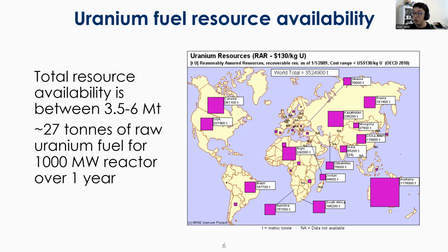So if you think about like a coal plant that needs to boil water versus a natural gas plant, which just sends air through the turbine and combusts the gas, right, in the combustion chamber, that's a lot faster to ramp up and be able to produce electricity than it is to heat up water and boil it to power a steam turbine.